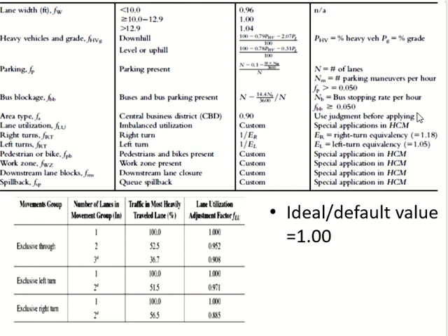What do we mean by equivalency factor? We use equivalency factor for heavy vehicles, remember? So what was that? How much does the truck equal the cars? Same thing. Now it is for left turning and right turning. So how much is left turning equal to through? And how much is right turning equal to straight? So these values are fixed.